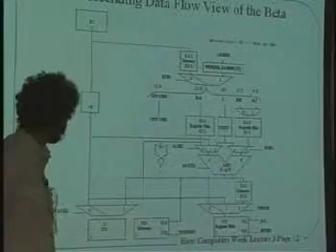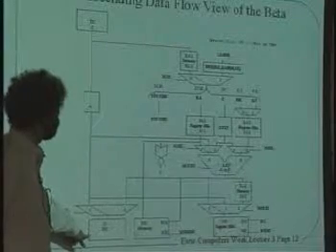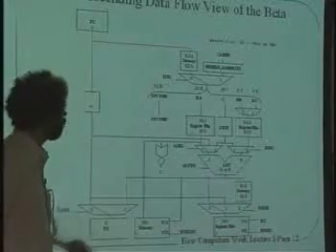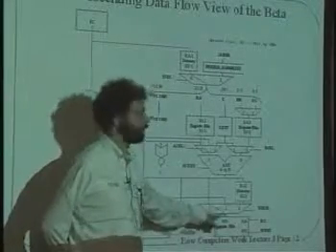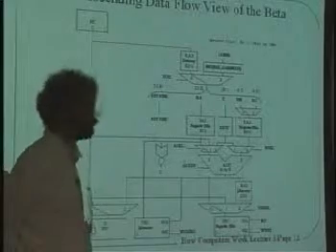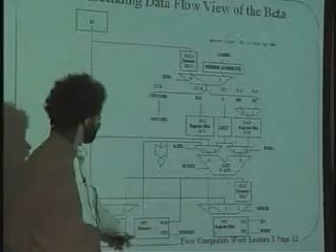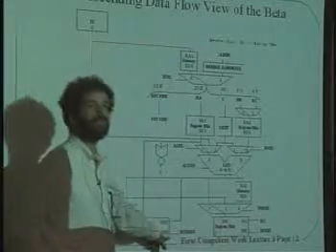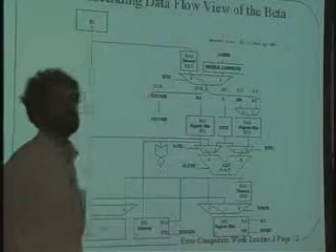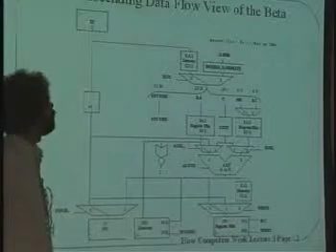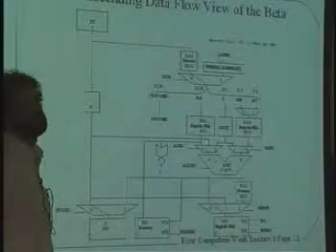What will happen is the PC will get the value of PC plus 1, and the register file will get the new value that's supposed to go into register C. And this guy over here, with WEMEM being low, will do nothing, even though the clock goes off. And that's how we do RC equals RA plus RB.